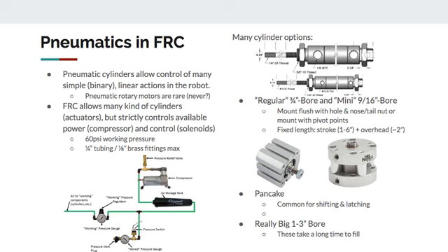There's actually a lot of flexibility in the rules as to what pneumatic outputs you can use. There are cylinders of all different sizes. You can get anything from a little 1/2-inch stubby movement. For example, we might use those in the gearbox when all you need to do is shift between one spot and another. The rules even allow you to use rotary pneumatic motors. It's kind of fair game there. The part where they get you is that you can only have so much air in the system, and you can only switch so much air at one time.